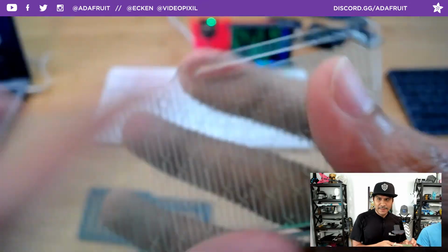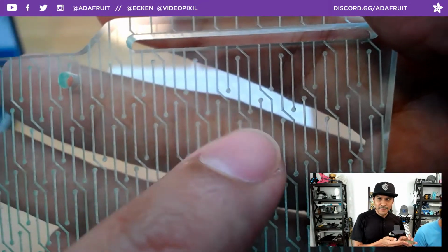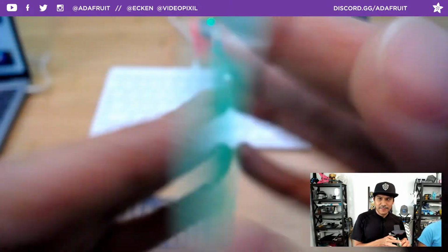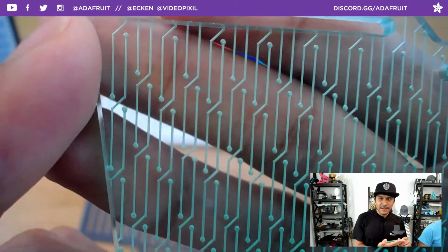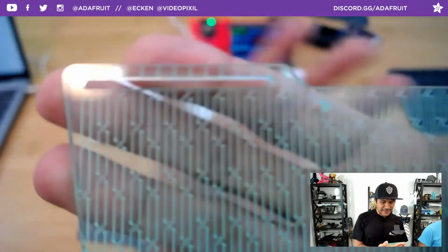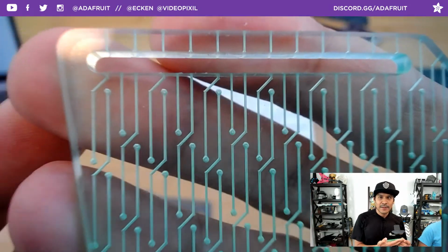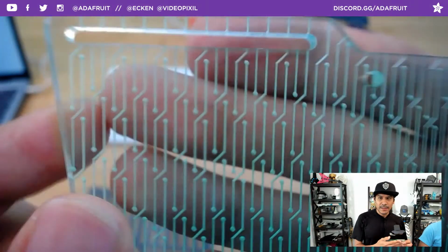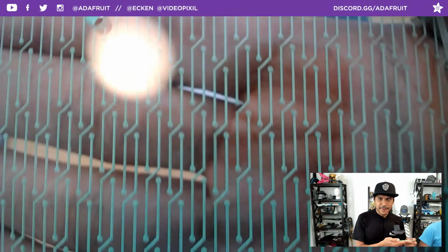And the tip here with engraving is, this is the surface that was engraved. You can see that it's not popping out. When you look at it from the reverse side, it really pops out because all the light is diffracting inside of those little cutouts there. As far as the depth of the cut here, we're looking at 0.4 millimeters of depth.